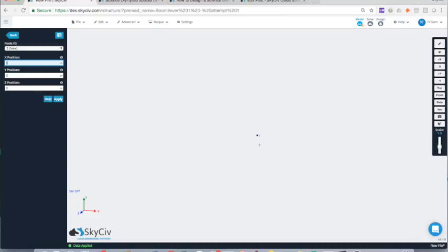And I'll build it out in the X direction, which is that way. We'll build something that's about 0.5 meter long. So I'm going to put 0.5, which is 50 centimeters. And you can see that node has been added in line with the first node at the origin, and if I hover over it, it'll show me that it's 0.500.